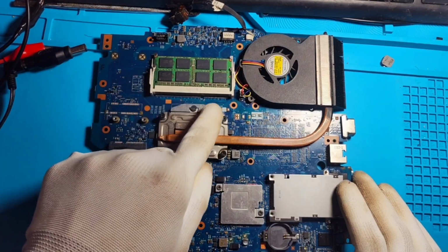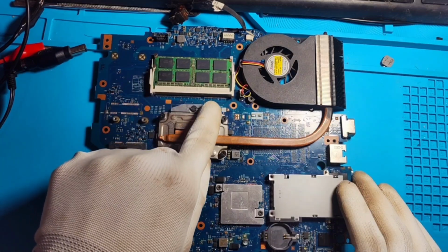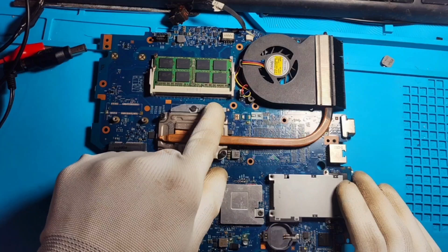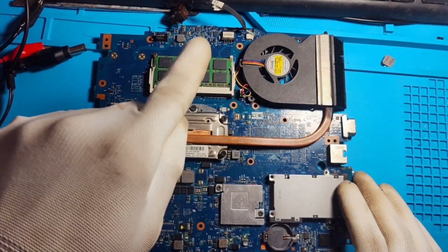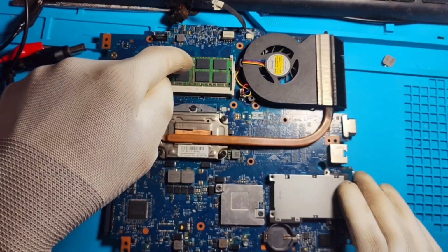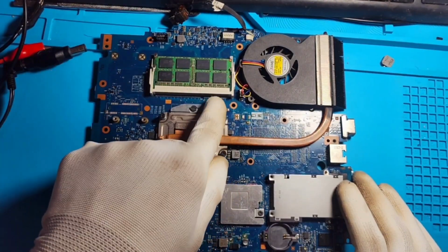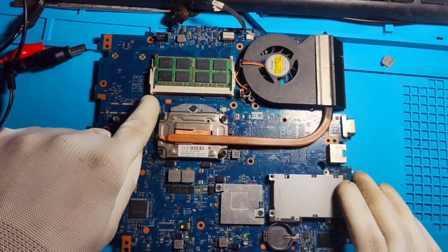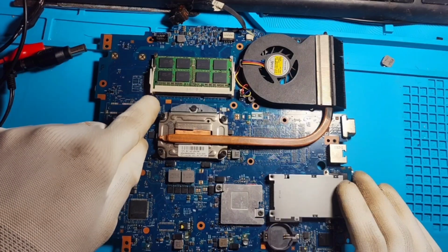We also need to check pin number 30 in the RAM slot to see whether there is a DRAM reset signal. The DRAM reset signal is very crucial for the CPU to initiate communication with the RAM module. Okay, so now we are going to check the DRAM reset on pin number 30, and we are going to check pins 200 and 202 to check the system data and system clock lines.